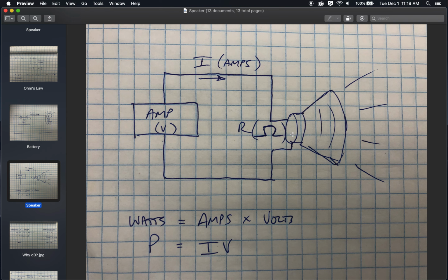So if you're just cranking it for hours and hours at a time, it all just wears out, or you can develop tiny holes, but over time, tiny holes become bigger holes, more holes develop, and that's where you get that really distorted, blown speaker sound. It's really from holes developing in the speaker cone.